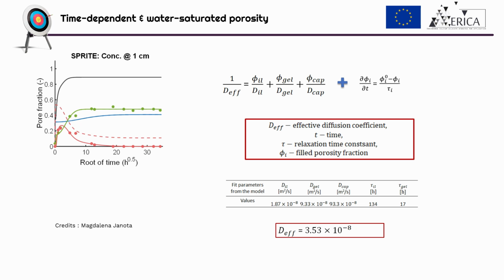In this subpart of the project, we developed a simple transport model where the input is obtained using magnetic resonance imaging technique. The one-dimensional magnetic resonance imaging was used to record water movement in a cement sample with spatial resolution. In the model, we assume that porosity is always relaxing exponentially towards a water saturation dependent equilibrium.